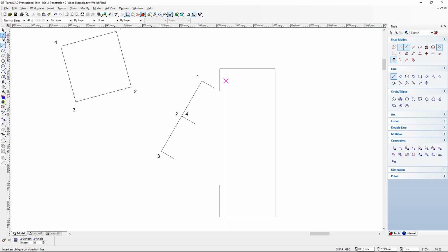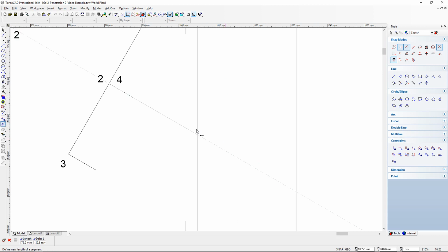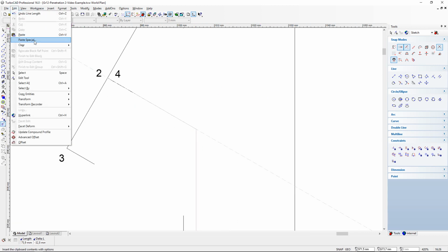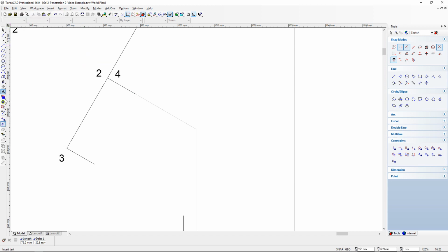And I need to just extend this angle of my front view, which is at an angle of 30 degrees, and therefore I can draw a light construction line 30 degrees towards this construction projection that I have created coming from the top view. All I need to do is make sure that they connect there, and then I can clear the construction.